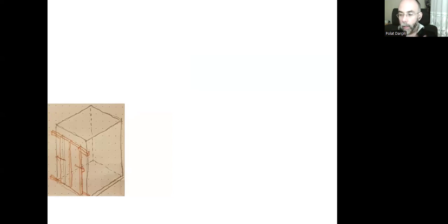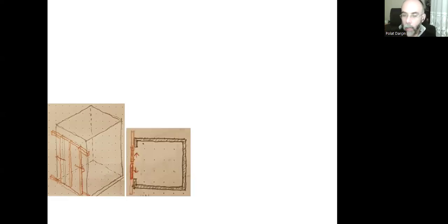We learned that on every floor there is a hoistway door which needs to be closed when the cabin is on a different floor because we need to protect the user. If the door is open and the user is careless, they can fall into the hoistway. But there's another set of doors on the cabin this time. Here on the plan, when we cut horizontally, we can show them like that. Generally, again, they're sliding doors. They don't necessarily have to be a sliding door. We can have different types of openings, but that's the minimum size.